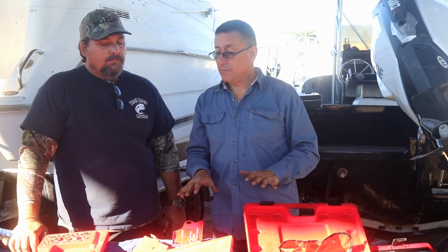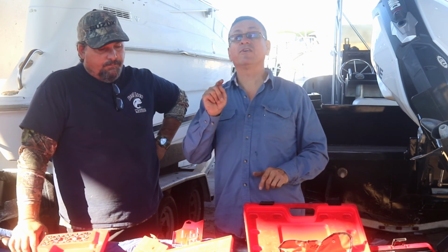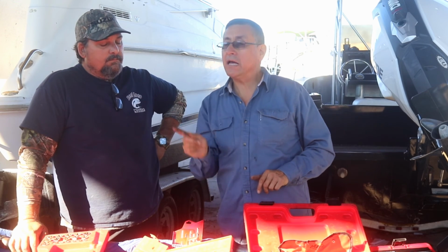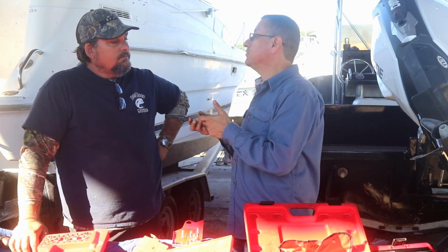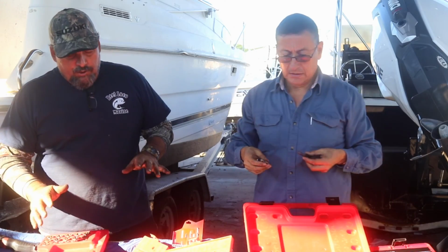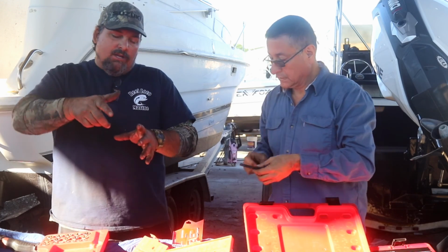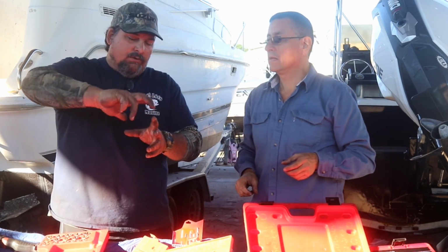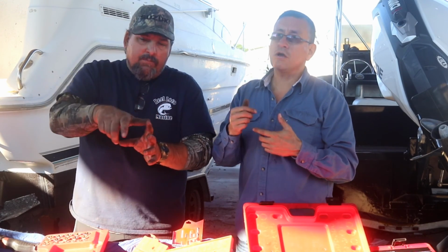In this particular example, you need a good set of taps and dies, a good set of extractors, male and female extractors, because in some cases you need to remove the bolt, in some cases you need to remove the nut. And when you're doing the tap, you don't just keep cranking. You have to go back and forth, back and forth. When you go back in, you go a little bit more. You go back out.